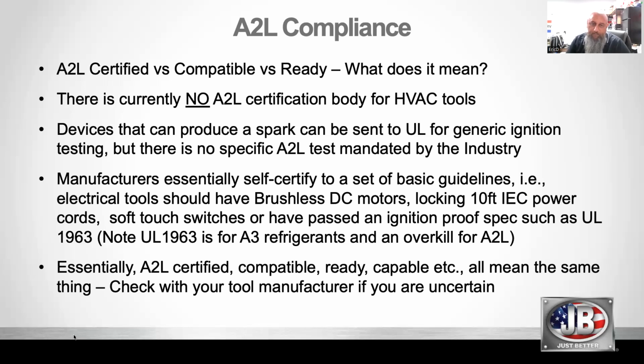I'm an engineer by trade. I'm a sales guy now, so I look at what they're saying, particularly about vacuum pumps, and I'm going, why? But I understand the other side of things as well. So if you're out there and you're using your old AC pump on an install, it's going to do the job, right? There's no refrigerant around, but you may run into other problems that are not ignition related, which potentially might cause you more issues in the long run.